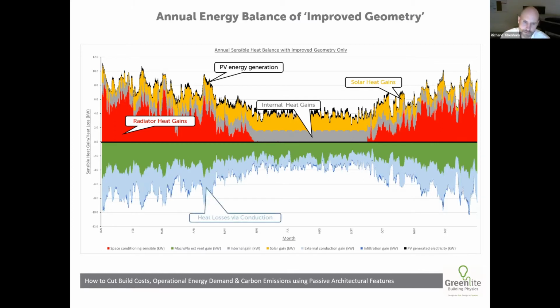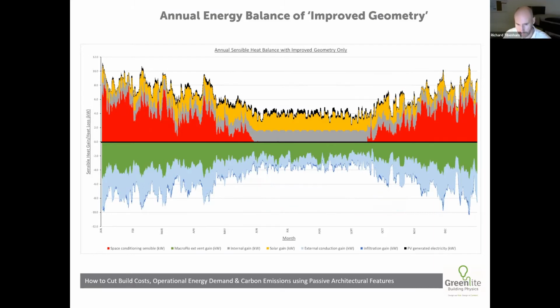In terms of the heat losses from the building, we've got the conductive heat losses. So that's conductive heat loss through the walls, the floor, the roof, the windows. And also the ventilation losses, bearing in mind that it is a naturally ventilated building. Infiltration, it was fairly airtight from what you recall. That's fairly minimal. So if we look at this wintertime season, which is the primary area of interest in terms of decarbonisation, big challenge is how we provide this low carbon heat.